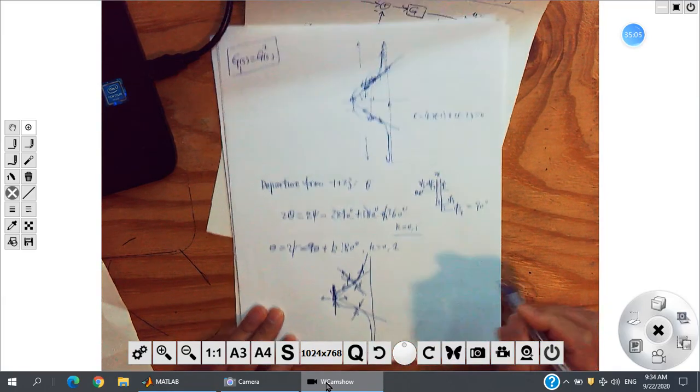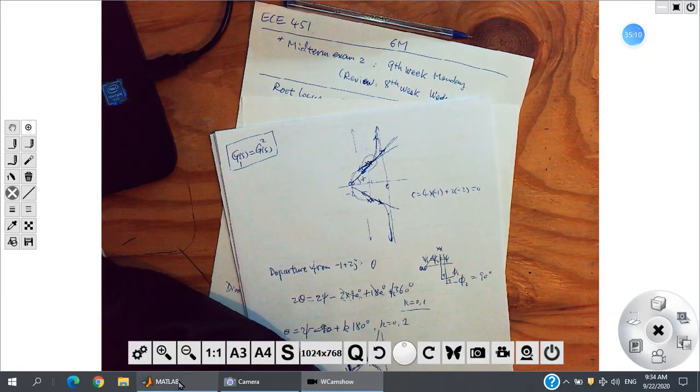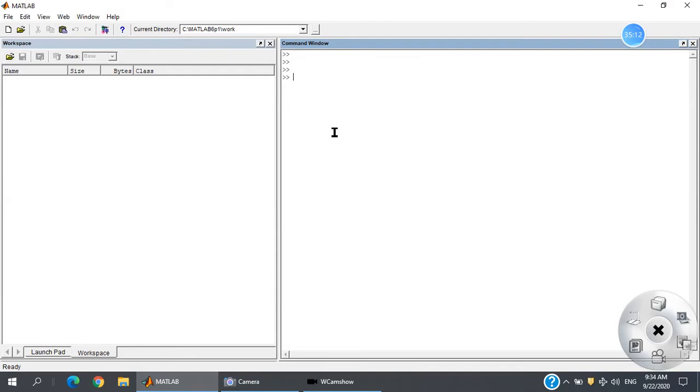All right. We can use MATLAB to see how it looks. I use s equal to this, and I use a g, whose numerator is s plus 2, so I have a zero at negative 2, and the denominator is s squared plus 2 times s plus 5.